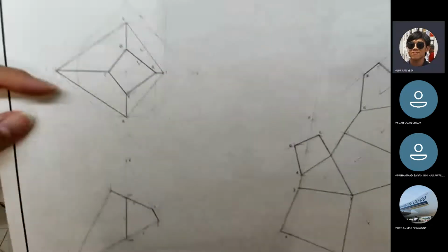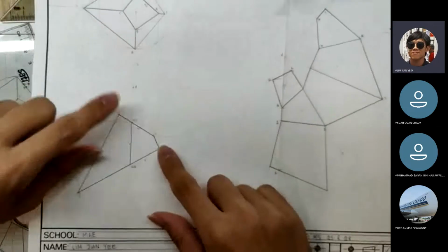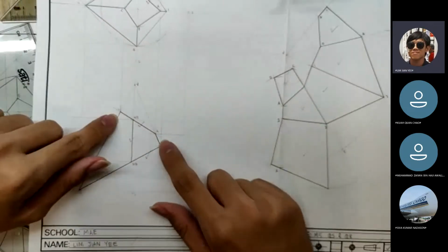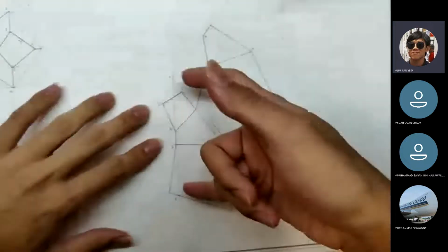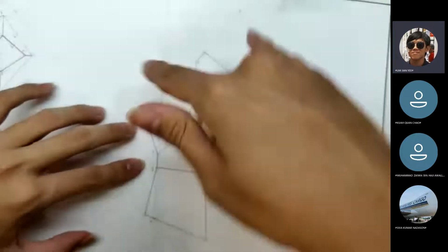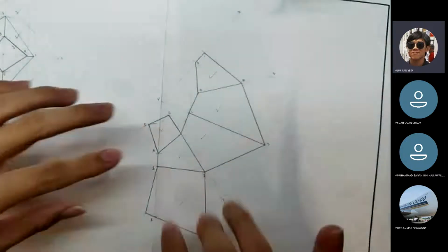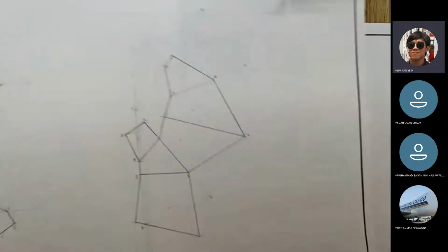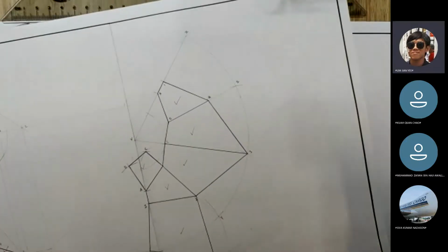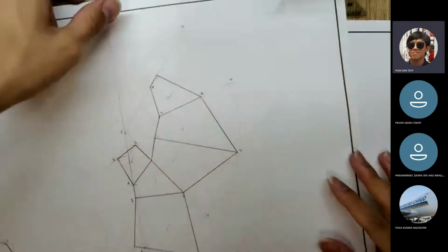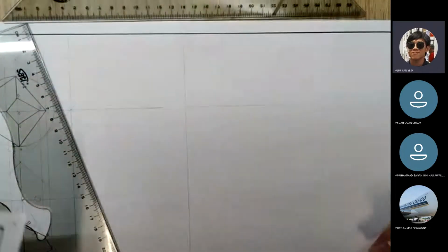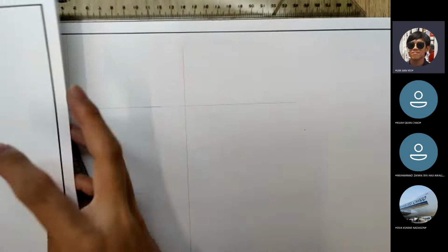Basically what you want to do is take every major point that is on a true length, like C, A, 1 and 3, and draw it completely, all the way through. The angle is at most 180, because sometimes it's more than 180, but for this question it only reaches up to 180 degrees.